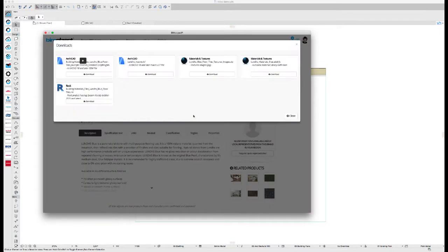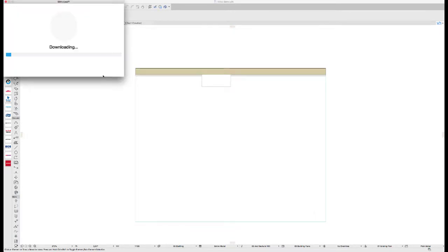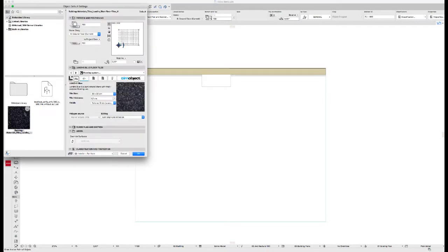So now we've loaded up the floor. In addition to the macro file, here we can control the settings. So here we have thickness settings, finishes, as well as the dimensions and the object specific properties listed here, which are also available for listing from within ArchiCAD. So once we've confirmed the settings of the objects, we go ahead and place that out into a project.